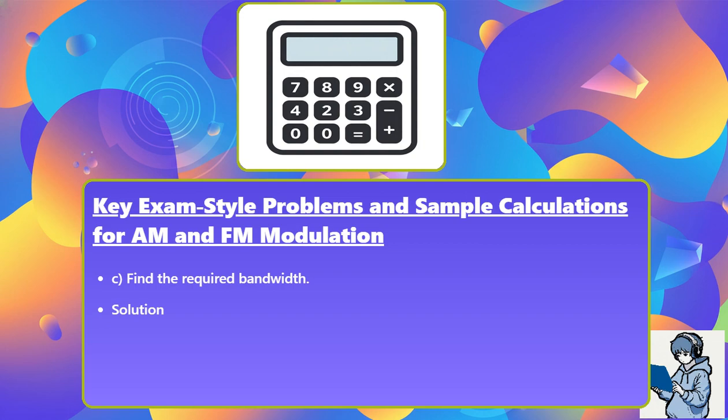Solution. A. M_a equals A_M divided by A_C equals 4 divided by 10 equals 0.4, 40% modulation. B. Carrier power, P_C equals A_C squared over (2R) equals 10 squared over (2 times 50) equals 100 over 100 equals 1 watt.